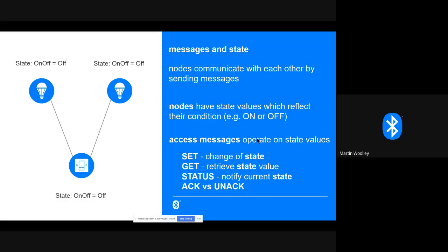And in the event that something doesn't go perfectly, maybe my device has to start resending messages, and very quickly 2 problems arise in the design. We get horrible complexity with very tightly coupled nodes, because every node knows everything about every other node in the network, so it can do things like track acknowledgements. And you get very, very poor scalability, because as soon as something starts to go wrong, which it will, because wireless communication is unreliable unless you do things at a higher level in your protocol stack, you can very quickly generate a storm of messages.